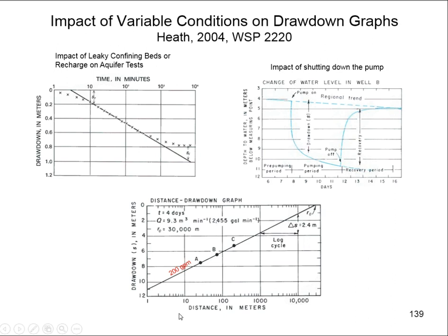And then this is kind of fun to do. If we are putting in a new well, and we want to make sure that we have enough drawdown, and we want to figure out the pumping rate. Let's start with what we have here. We're going to put in a well at 10,000 meters away. And at 200 gallons per minute, we have about 1 meter of drawdown. But I want to pump at 100 gallons per minute.